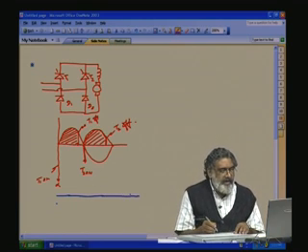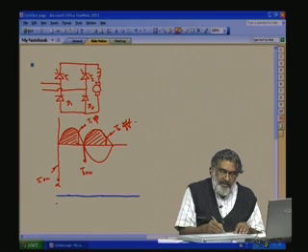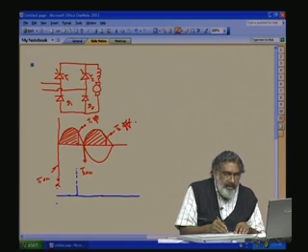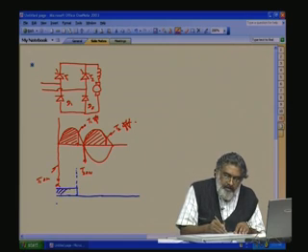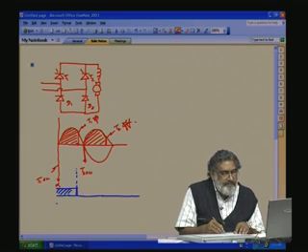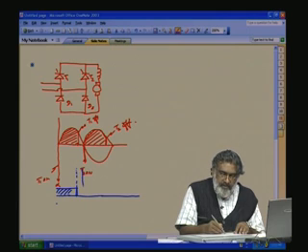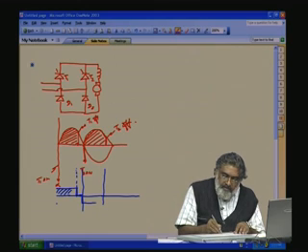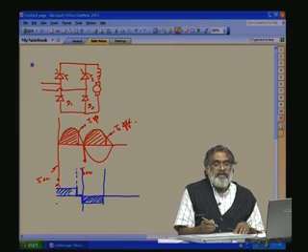If you take the current waveform, at this point freewheeling starts where beta is there. So, the current waveform will be here, comes here, till this side it will be 0, then again it goes negative here. See, this way it goes.